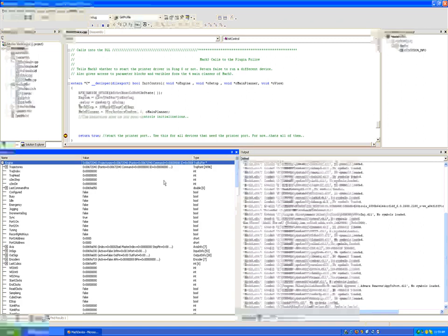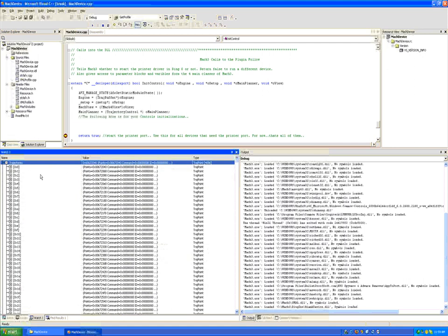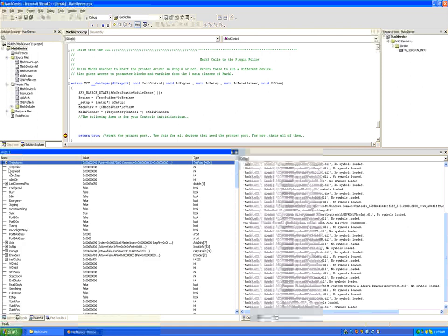You can get them and change them by using the pointers provided. You can see that there are structures. There is, for example, trajectories. Trajectories is a list of all the commanded moves which have not yet been sent out. Traj index and traj head are ring buffer variables pointing into trajectories. When there is movement going on, these variables will point into movement information in the trajectories queue.